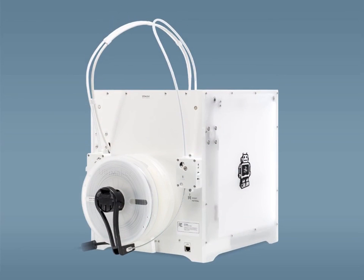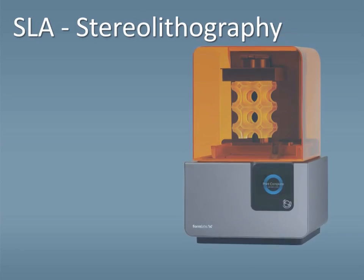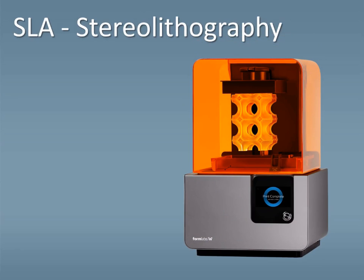These materials are typically coiled around a large spool that attaches to one of the sides of the printer. This allows for the strand of plastic to feed up and over the top of the machine into the moving extrusion nozzle. Now I'll switch over to discussing which types of materials are used by stereolithography 3D printers, or SLA printers. These printers utilize the process of photopolymerization.